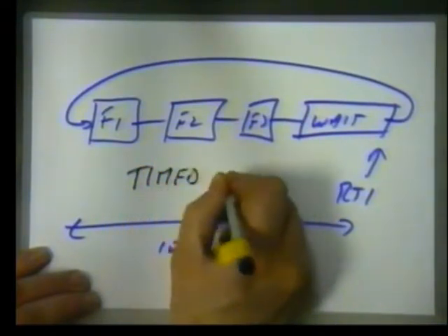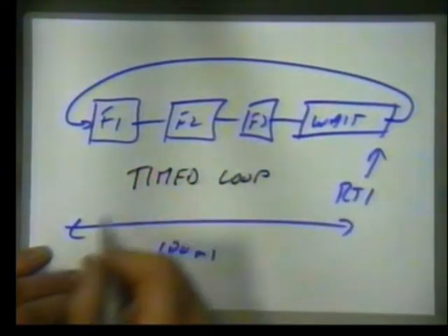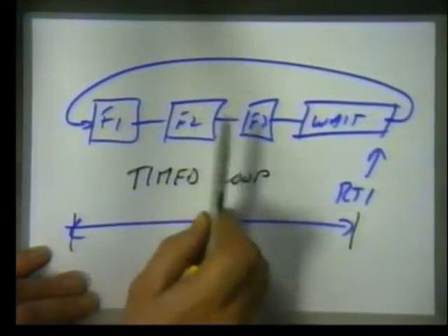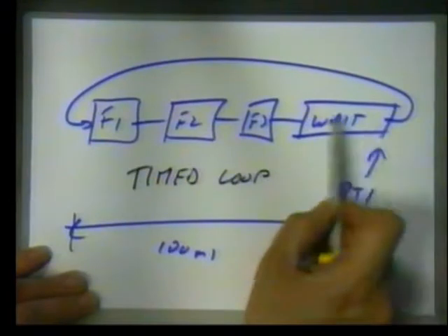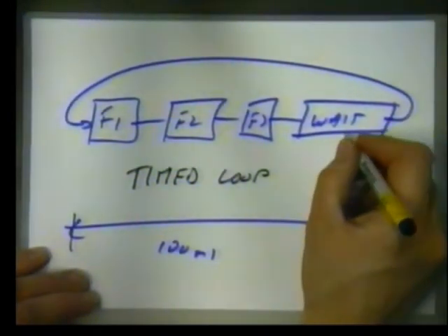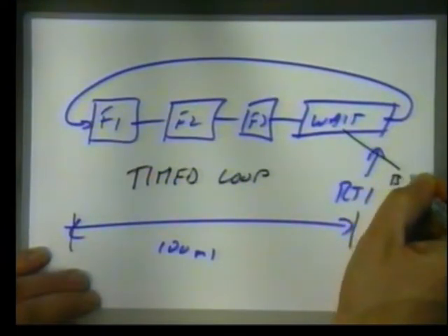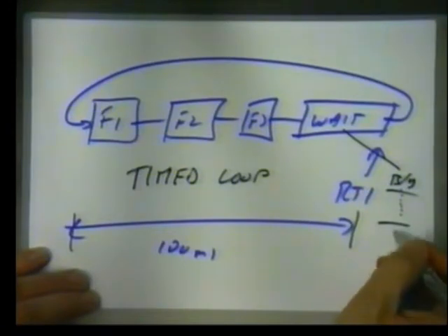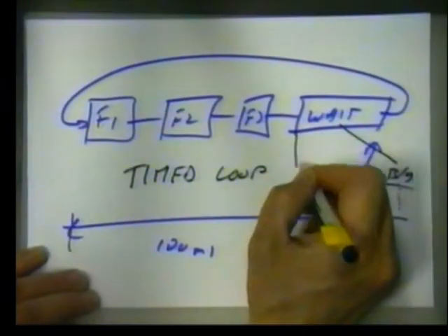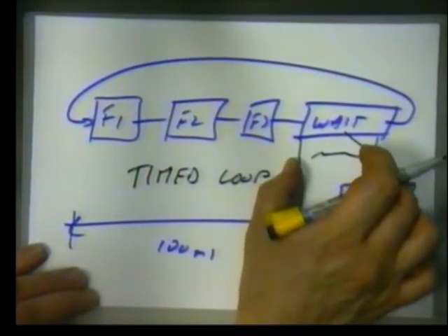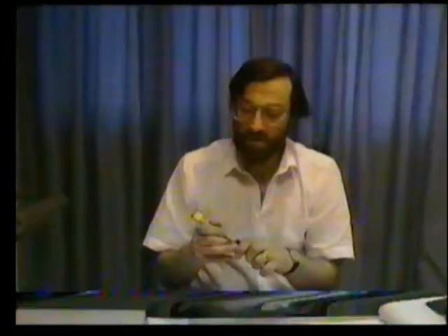It's just a timed loop. Very simple. In a fixed time interval, we will always do that, that, that. And if there's time left over, you do nothing. Well, I suppose if you want to make that a bit cleverer, why not now implement a little background routine and let that fill up the time? And that way we can actually make use of all the spare time to do some slow housekeeping that you can suspend. So you can add a little bit more complexity.